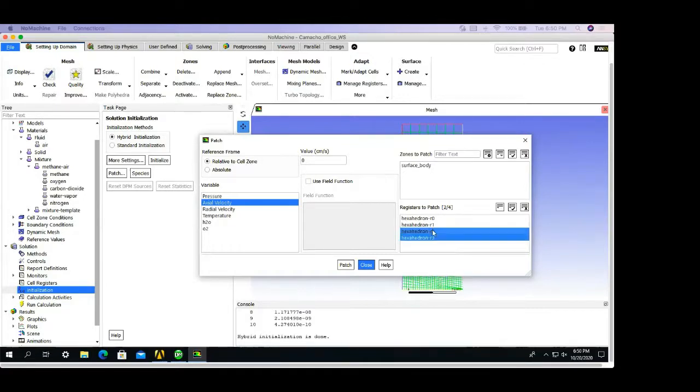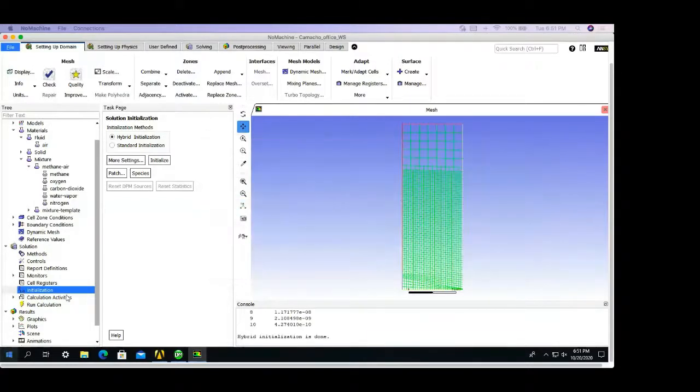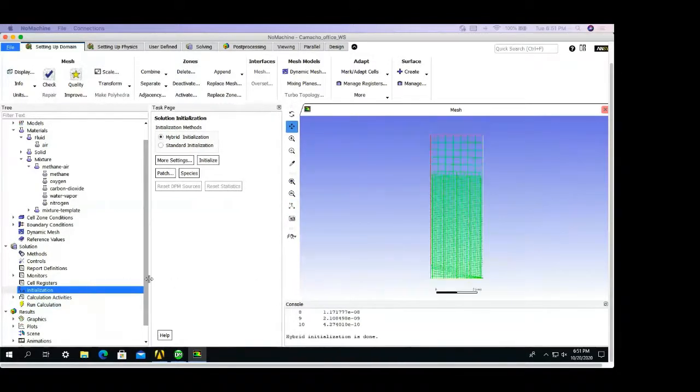And then finally, in our post-flame zone, it's more CO, CO2, water, and again argon. So those kinds of major species. Basically, we initialize some of the major species in this patch. So you do that for each zone, and then you're ready to run it.